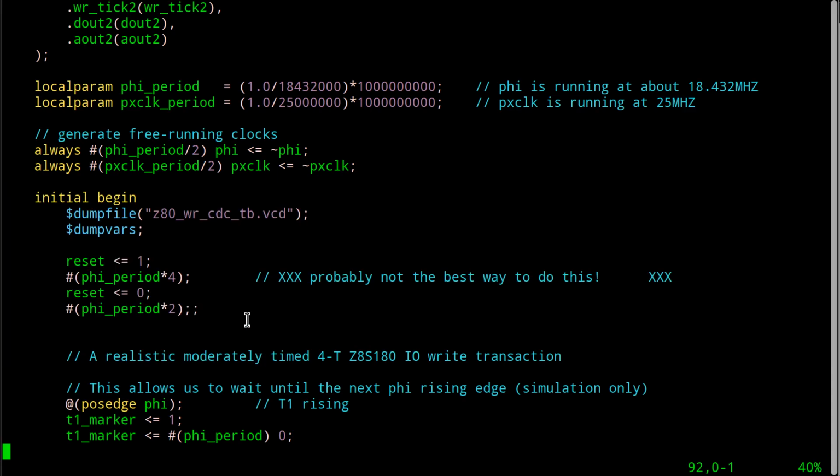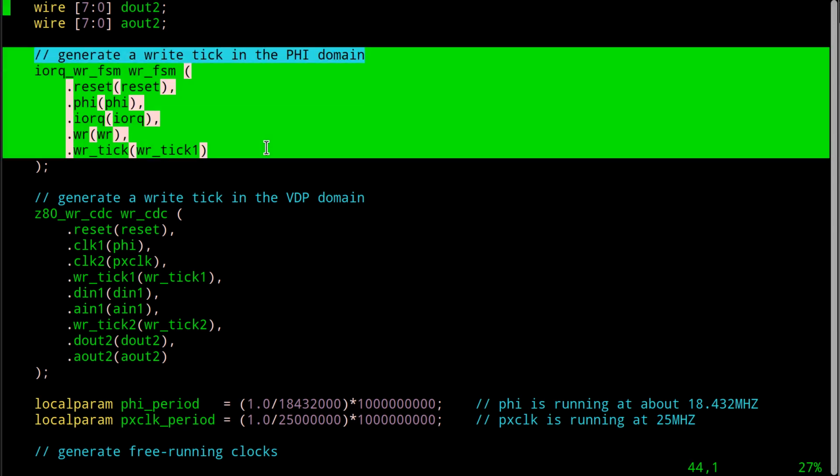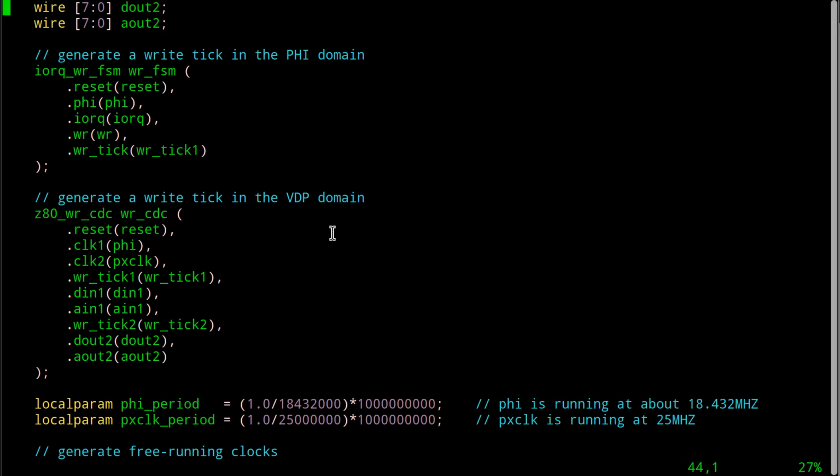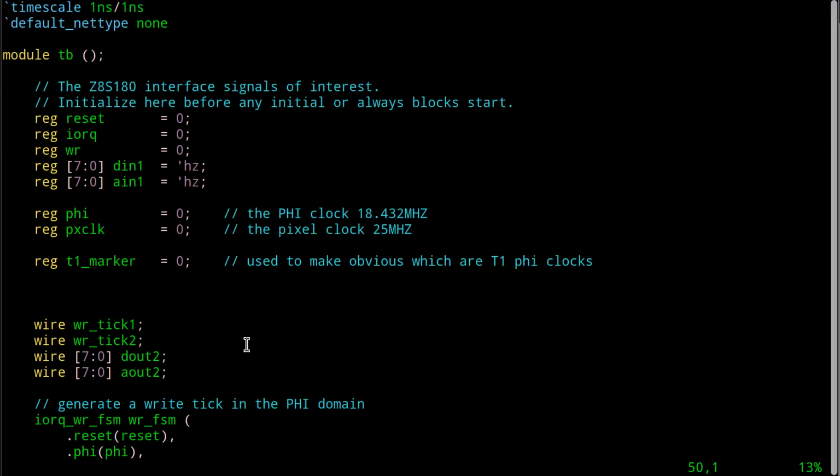And you don't really know which one's going to go first, which is the blessing of how Verilog runs its always blocks. It could be this one, could be that one, could start the initial block. It could be an initial or an always block in this module under test. It could be an initial or always block in this module under. How do I know? Nobody really knows. And if something uses one of those signals right off the bat, there could be a problem. But if I do it up here, it's assigned before anybody does anything.